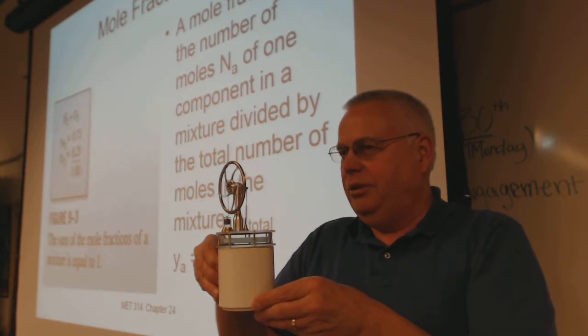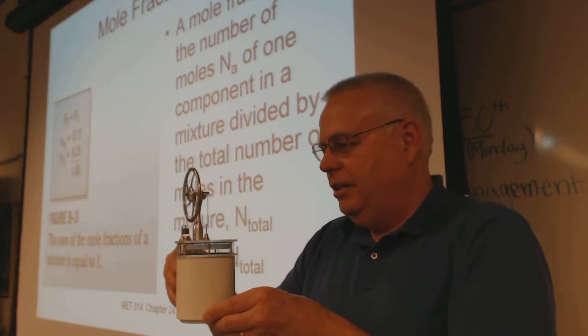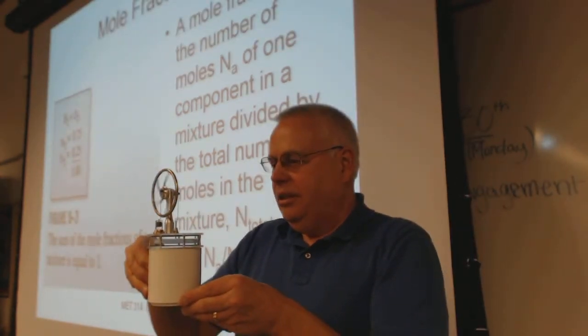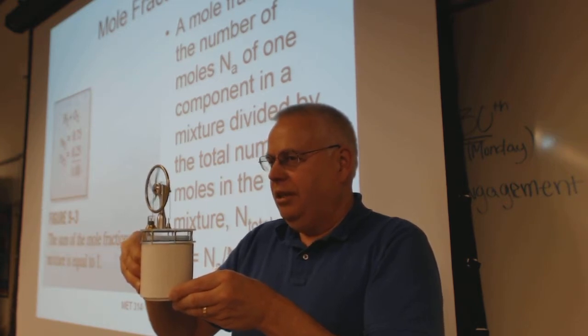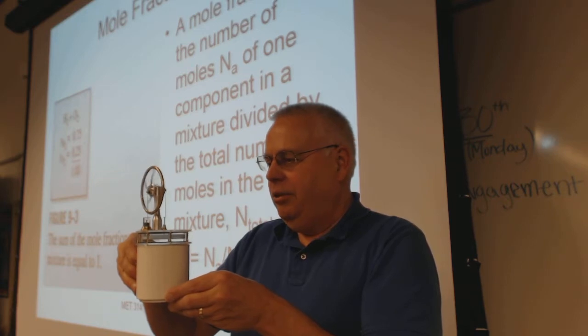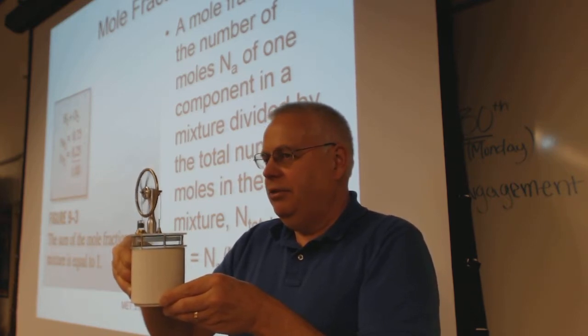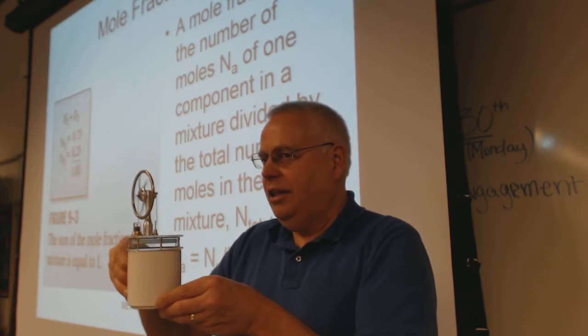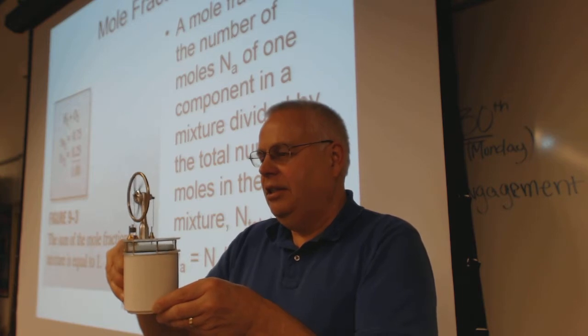You see the little power piston in front, and a displacer piston. The area with the blue piston going up and down, that's the air. When the blue piston goes up, most of the air is on the bottom surface, which is hot, and the air wants to expand, and when it wants to expand, it pushes the power piston.